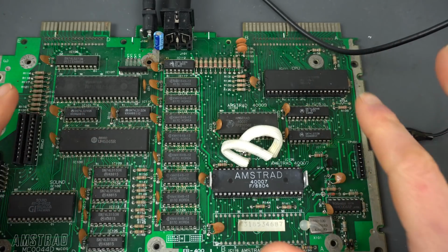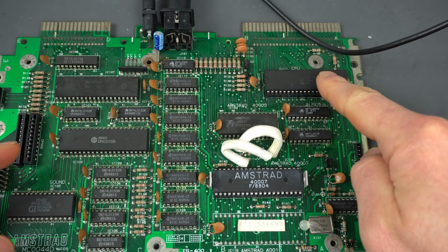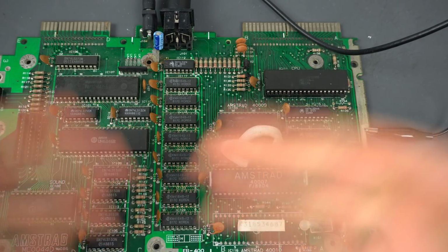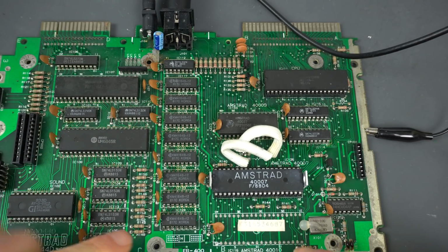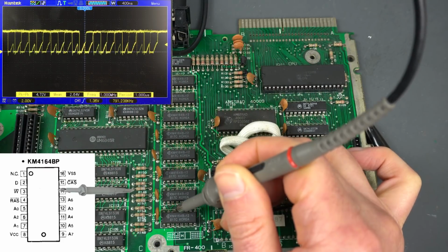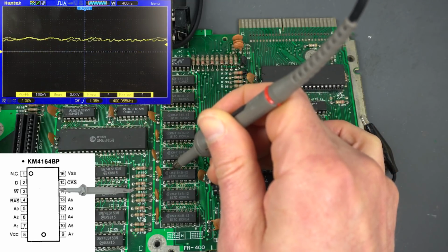So thinking some more along those lines, another possibility, if the ROM is fine and the Z8 is fine, is that the data bus was or is being clobbered by something. We could look directly at the RAM chips. Okay, that seems reasonable. Some activity there. It never looks particularly pretty.